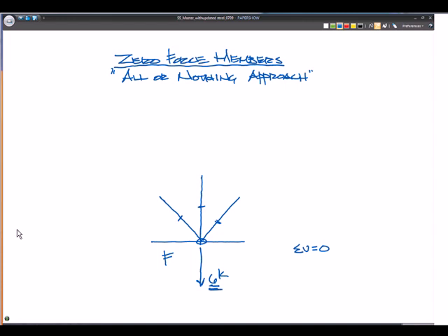So let's assume that all of the force goes into that vertical member that we're testing to see if it can take any force at all. So if we have 6 kips down, let's assume that this member gives us 6 kips going up. And let's assume that all of the force goes into the vertical member. The test is, can we do anything with it at the other end? And here is joint Q. So if we're going to assume that there's 6 kips of force in member FQ and it's in tension, then this member here has to be 6 kips of tension as well.